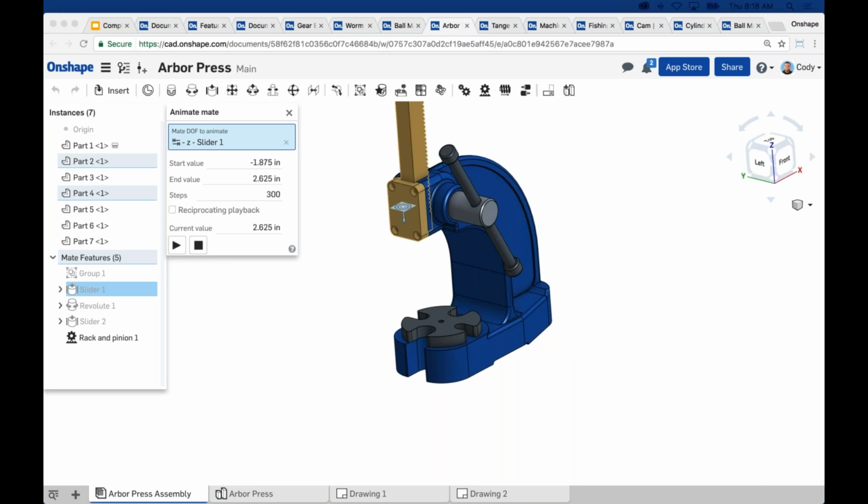I noticed the double cog gear had two different rotation rates. How do you set up gear relation to have two different ratios per revolute mate? I'm not sure I follow. If we're referring to three sets of gears, then we may be referring to two different mates. All we're doing here is defining a ratio of the first to the second. So I'm entering that ratio in. There's not two different values per one relationship.